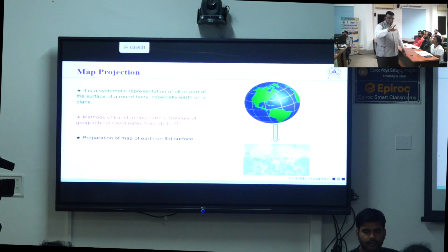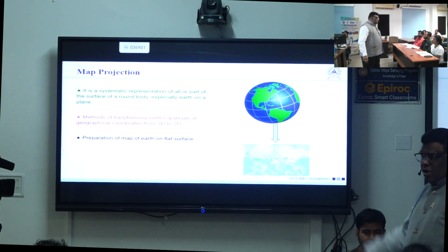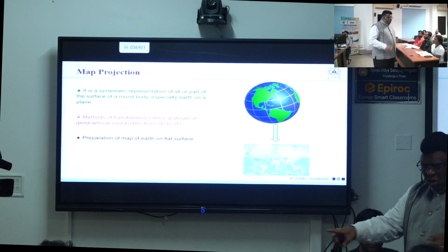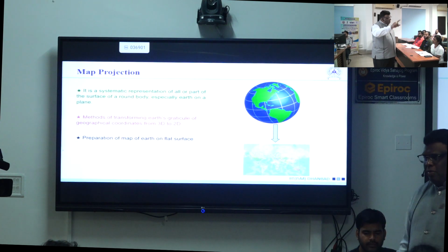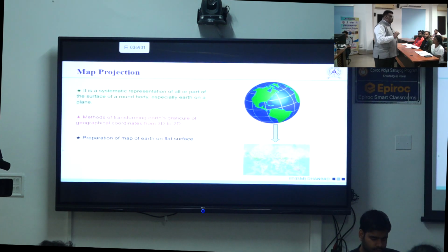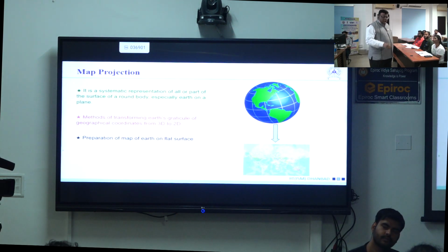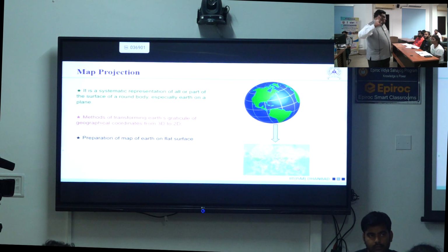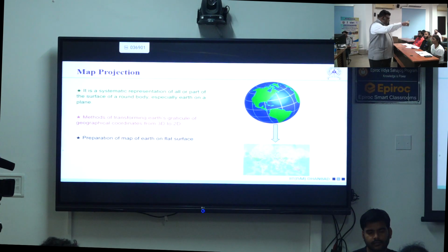Yes, this is what I want to cover: map projection. Actually, how is the real world? The real world is 3D, circular. But we are representing that in 2D, 3D to 2D. In survey also, if it is a small area, you take it as linear. But if it is a bigger area and your project is very significant, you have to consider the curvature also. So here the 3D is there, and you are representing it now in 2D. How is it possible? Obviously some error will be there.